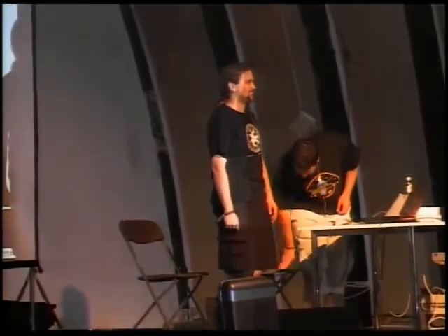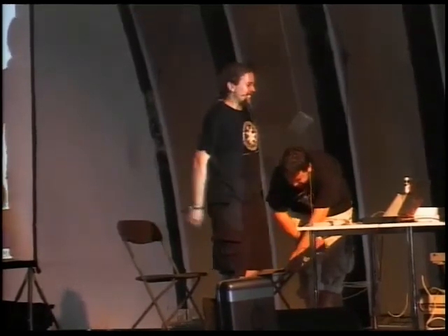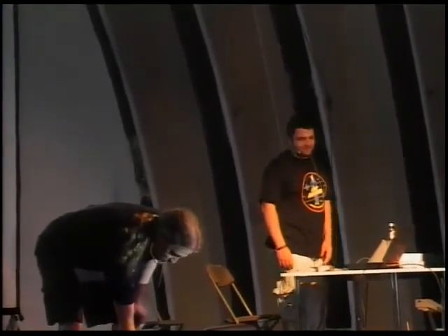Well, on the topic of religious belief, I typically keep my soldering iron set at 666 degrees. That works well for me. I have yet to burn anything out. For sensitive electronics, a range between 600 to almost up to 800, maybe 750 or so, can safely be used. You might want to go higher if you're desoldering, because that generally goes faster if you're using a wick to pull the solder out. Yes, I believe Fahrenheit. Yes, Fahrenheit.